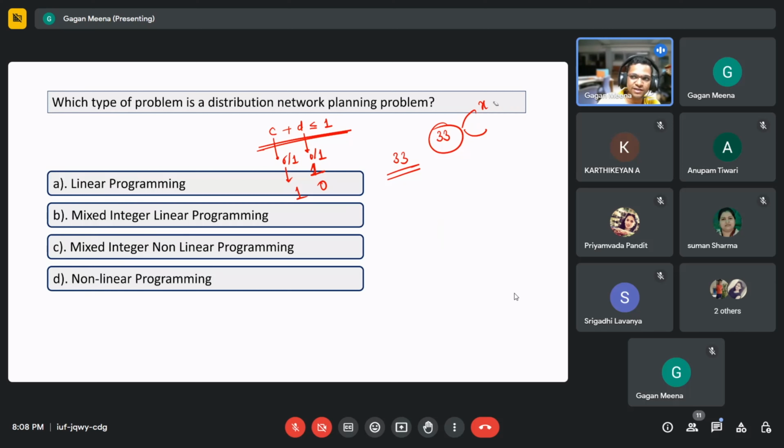So that x variable will be 0 or 1. If it is in the final solution, if it is there at a bus, then it will be 1 at that bus. For other buses, it will be 0. In the case study that was considered, energy storage was sited at 4 buses. So at 4 buses that variable would take a value 1. At other buses it will be 0. So that's an integer variable, in this case a binary variable. Is it clear?